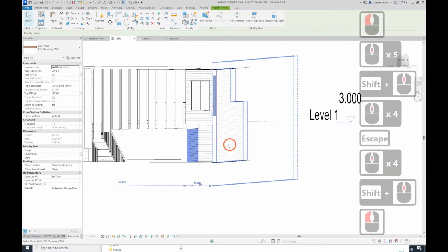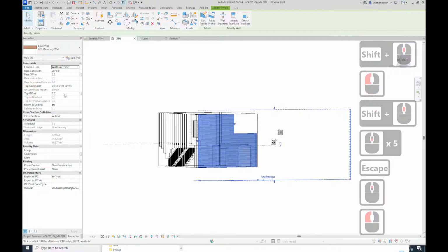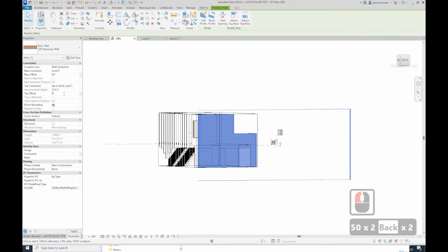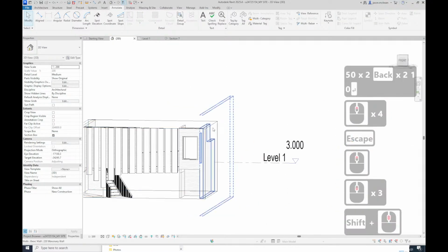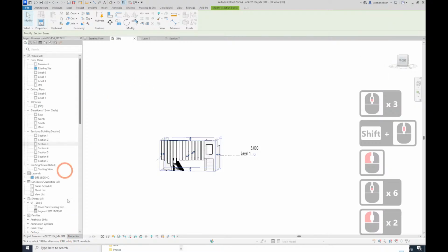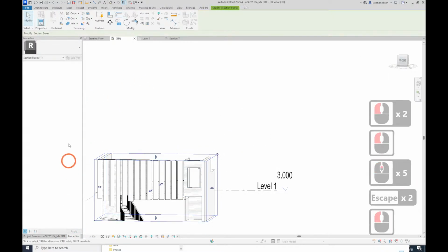Oh, so that starts on top of the slab and not beneath the slab? Yeah. So for my roof, for my parapet, I can take it 510 past, because that's a couple of brick courses past, and you'll see it'll take it past. Sorry, this is a section box interfering, so let me just switch that off. So it always stops beneath the slab, not in the slab. So that's something you've got to remember, okay?